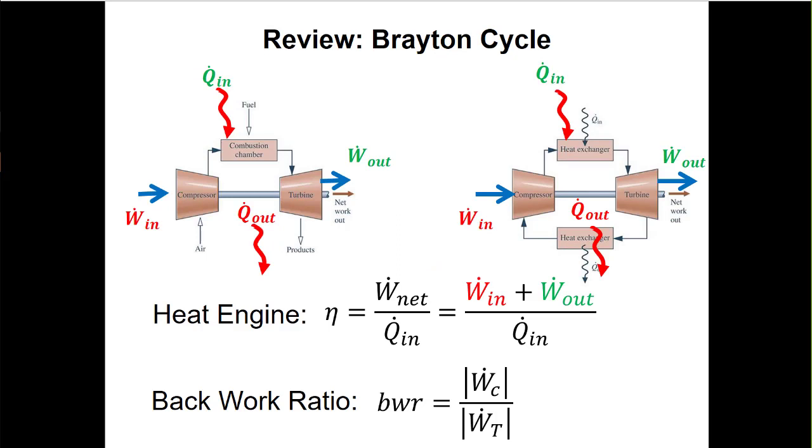So the first thing that I like to do, especially after we get these weekends, right, is review a little bit what we've been doing, right? So we talked about these Brayton cycles, right? A Brayton cycle is almost the same as a Rankine cycle when we think about our three questions, right? So it's a heat engine, so we need to know the net power and the heat in, right? That's how we characterize the thermal efficiency.